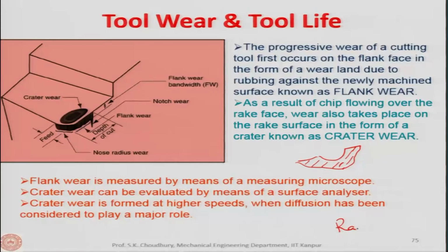This movement is very sensitive, and it is amplified and measured in a device, which gives you the actual surface roughness in microns, whether it is Ra or Rz.